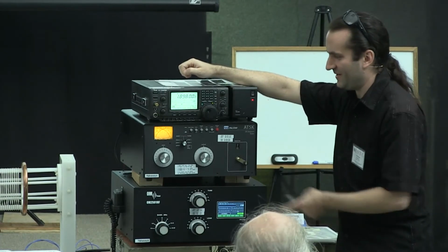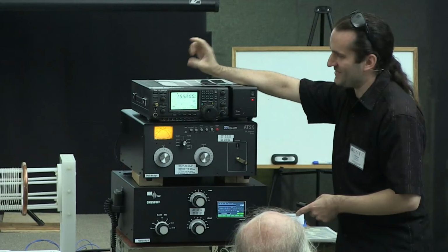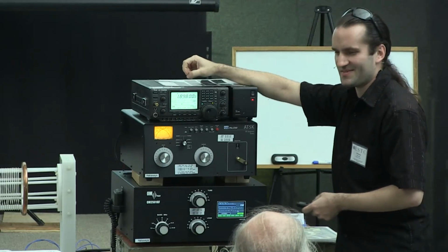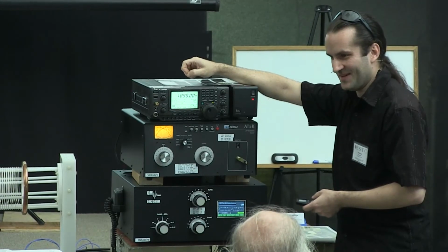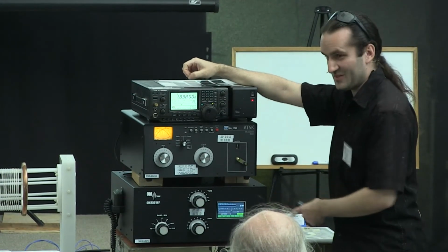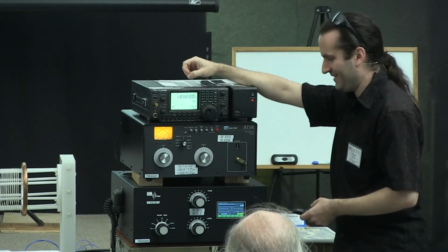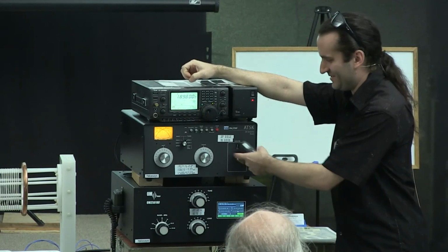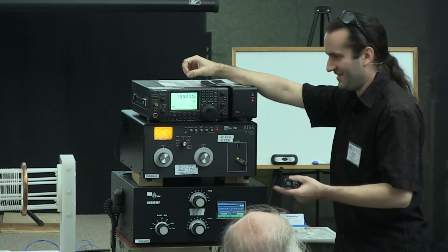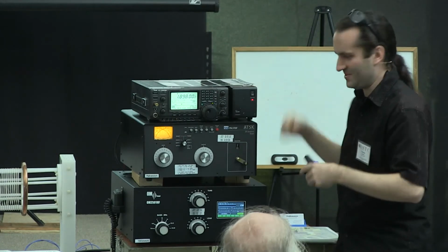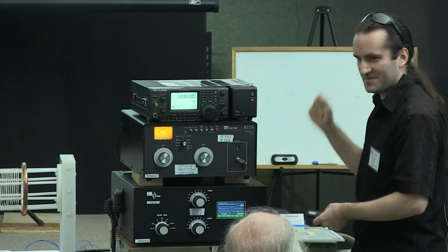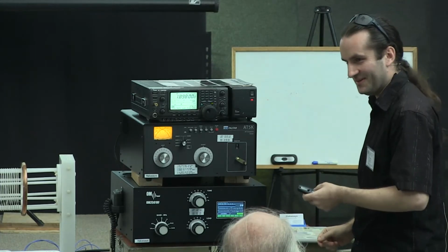But it turns out that Tesla coils, because they have such a tight tuning, they're not designed for ham radio, apparently. You're not supposed to run Tesla coils with a ham radio. So I had to make some modifications to the transmitter to get it to work properly. But even with that, the tuner can be a bit of a pain because you move your hand 2 feet away, and at a kilowatt, you throw the frequency off, throws the SWR off, the thing trips itself out, and you're back to square one.